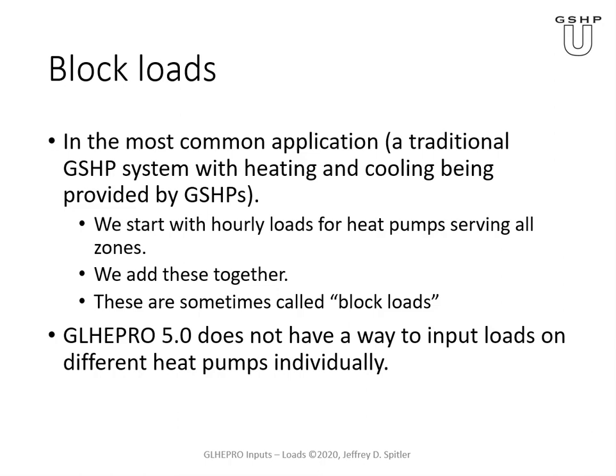All right, and GLHEPRO, at least 5.0, doesn't have a way to input loads on different heat pumps individually. I considered that some years ago, may yet change it in the future, but at the time it seemed like it would be overly complicated, at least for an American system where you might have 15 heat pumps in a small office building or 30 heat pumps.